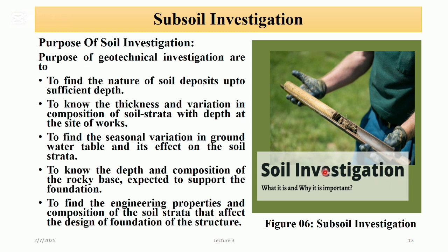We do the soil investigation to find the nature of the soil, to know the thickness, variation and composition of soil strata with depth, to find the seasonal variation in the ground water table and its effect, to know the depth and composition of the rocky base expected to support the foundation, and to find the engineering properties of the soil.